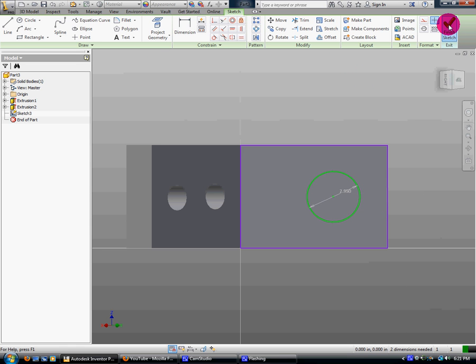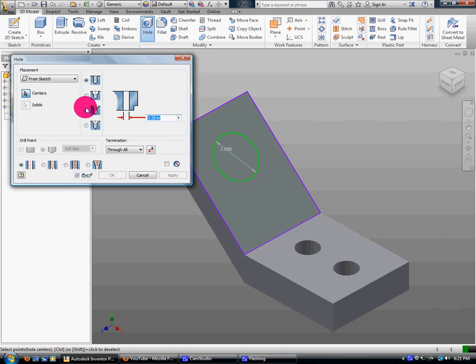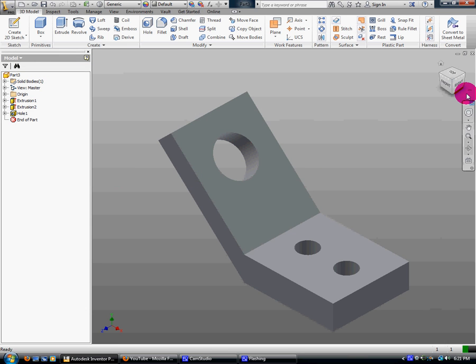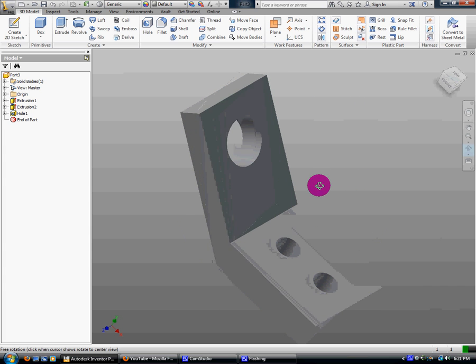Now, I'm going to finish the sketch, and I'm going to use the hole tool. Before on this one, we drew what we needed to do and we extruded so it had the holes. Well, now I've drawn a solid surface, and now I want a hole in the middle. So I'm going to go to my hole tool. I'm going to tell it what's the size of the diameter. It's going to pick the center point here. And then I have to tell it, do I want it to go a specific distance? Do I want it to go through all? Do I want it to go to a different plane? There's different options we can pick. But for right now, let's just do it through all. Perfect. Spin it so you can see. See, we have a hole.